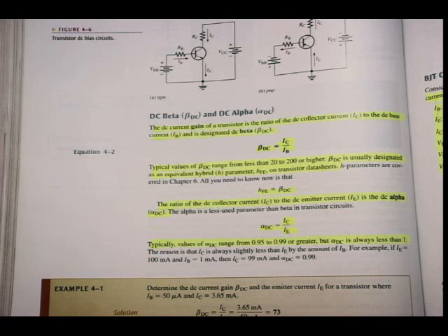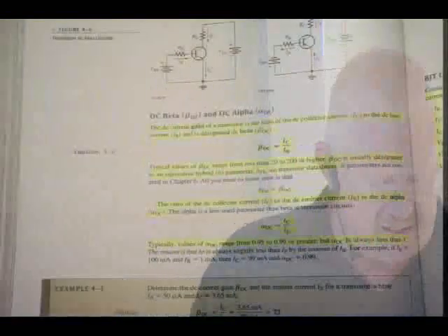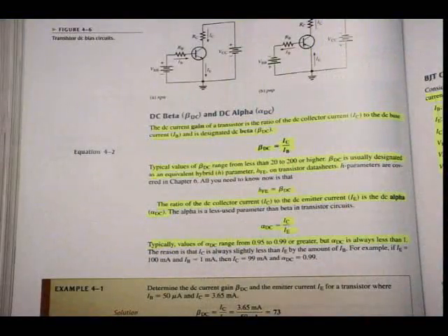So what can I see? The current IB is very small in comparison with either the collector current or the emitter current. But I can see that the emitter current is the largest, so by the magnitude of IB, it will be larger than IC. But actually, IB is so small, in some cases, as you will see later, I will assume that IC is equal to IE to do some of my calculations. So what I can see from this formula, beta DC is equal to IC divided by IB.